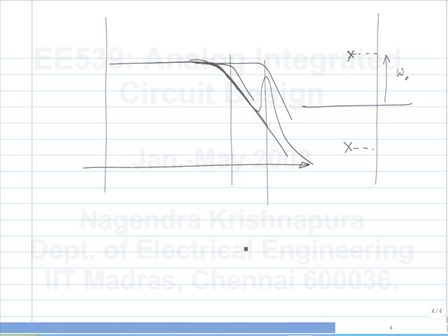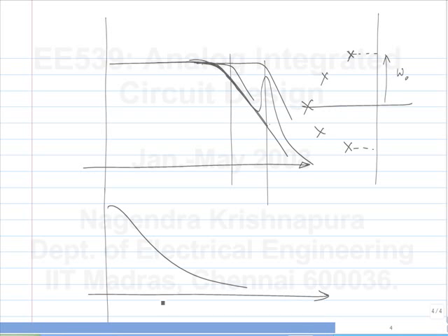So I think you have taken courses on filter design, right? So there also you do the same thing when you have higher order filters, like you will have poles something like this. There will be something with a low Q that has a frequency response like this. The next one will have a tendency to ring but not too much somewhere here, and the next one will have greater tendency to ring. So the combined effect will be a flat one. Okay, or maybe something that undulates slightly and then falls out.